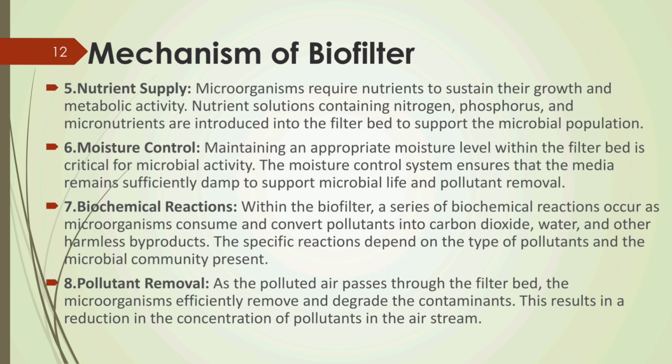Fifth is nutrient supply. Microorganisms require nutrients to sustain their growth and metabolic activity. Nutrient solutions containing nitrogen, phosphorus, and micronutrients are introduced into the filter bed to support the microbial population. Sixth is moisture control. Maintaining an appropriate moisture level within the filter bed is critical for microbial activity. The moisture control system ensures that the filter media remains sufficiently damp to support microbial life and pollutant removal.